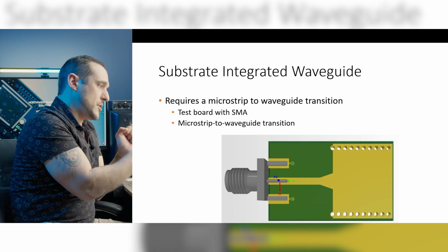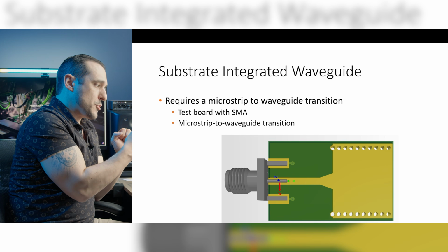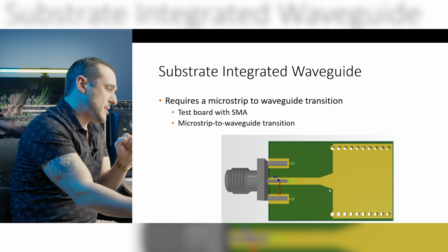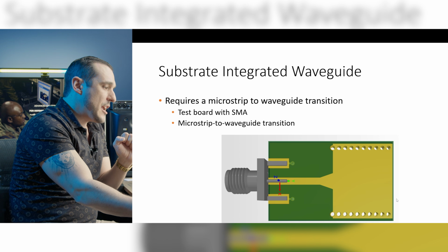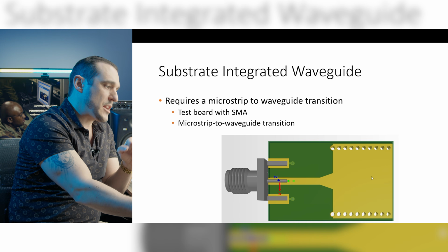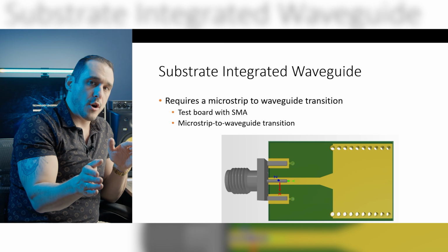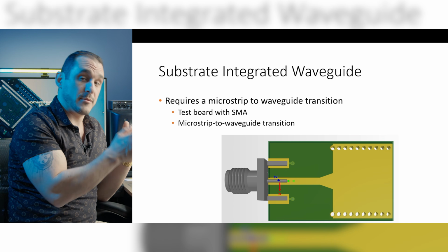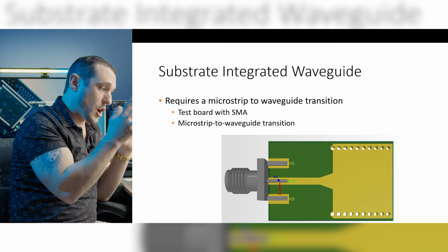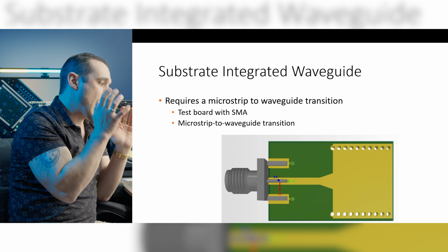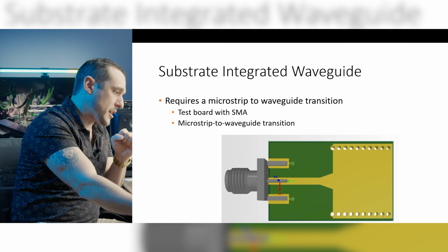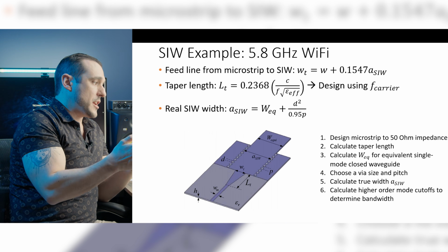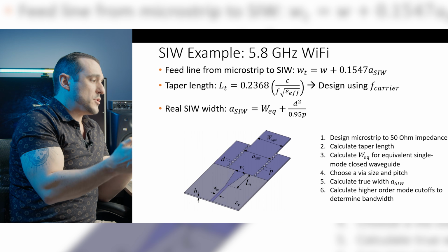The pin then touches a microstrip. The microstrip goes into a transition using a taper, and then that feeds the signal into this substrate integrated waveguide. Here on the right-hand side, you would have emission at a very specific electromagnetic mode, which could then couple into, for example, a metallic waveguide. And that's actually the most common application where I have used this type of interconnect design.